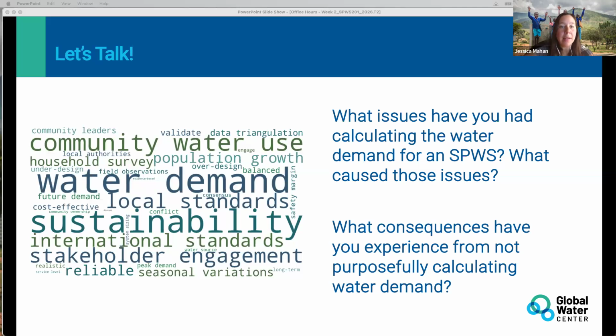On the high end, we would really only recommend no more than 3 times, and that's a water quality issue. We don't want water sitting in tanks too long, especially if we're doing inline chlorination before it gets to the tank, because you might lose your chlorine residual if people aren't using the full amount. And you might have some water quality issues if the water in that tank is not turning over every couple of days.